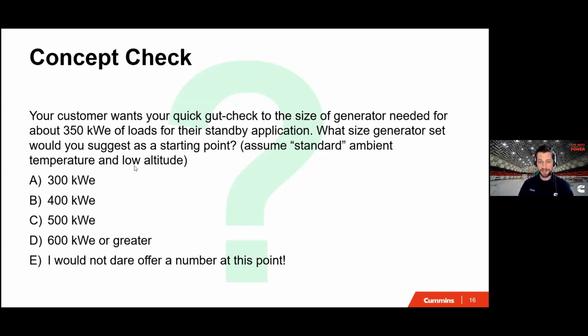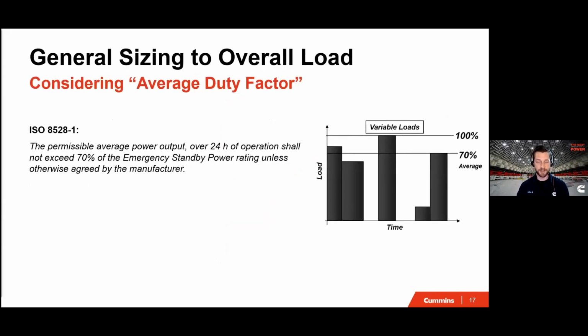Thank you so much for engaging with that. So let's dive in a little deeper about why I asked this question, because this next section is all about sizing to an overall set of loads. So I'm slowly getting more specific as we go through this power hour. To answer the question in the most generic terms available, I'll first refer back to ISO 8528. I didn't mention this before when I mentioned variable load profiles that are expected of a standby use generator set. But right there in the description of variable loads in ISO 8528, it goes into more detail about quantifying that variation in the loads.